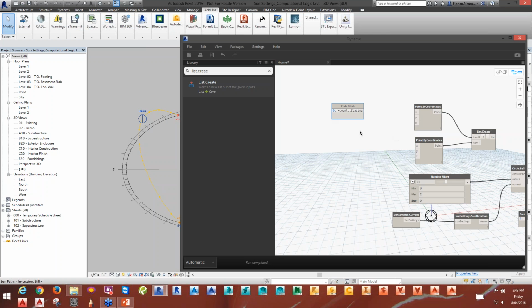So what does this create? It creates one output, and I just click on the outside, and you see on the left-hand side here spacing, and there's no 0. On the top again, we get a little bit of an error message. Warning: values used in this expression must be a number or a letter. It's complaining about this, but sometimes you need to tell it a little bit. Be patient, Dynamo. I will satisfy you, and I will help you in a second.